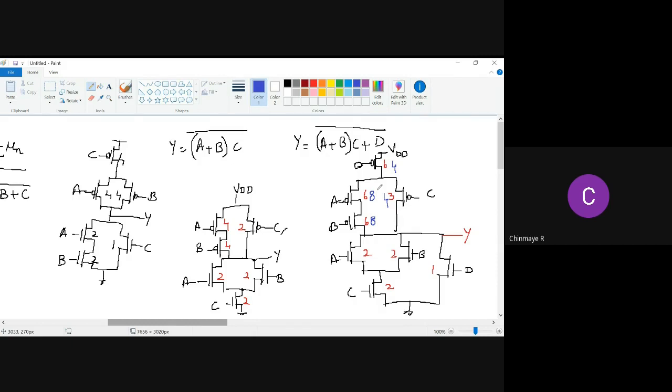Even in our college we have a tool in Cadence. There's a tool called Genus in Cadence for synthesis from Verilog code in order to create a netlist. If you give Verilog code as the input to Genus, along with all the constraints like my clock is this much, I have this many inputs and outputs, all these details, it will give you a synthesized netlist. The name of the tool is Genus, from Cadence. You can try this. It's very interesting.